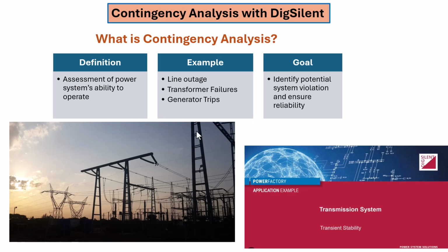Because wet coal may cause a number of issues, one of which might be transportation or issues with the combustion, because wet coal is harder to dry in the mills, which can negatively impact the combustion to basically power those steam turbines.